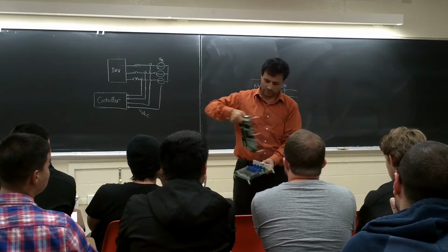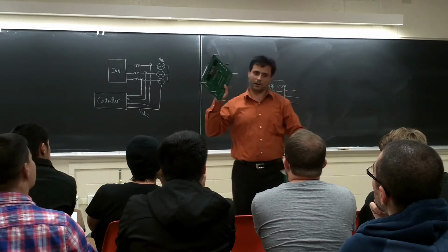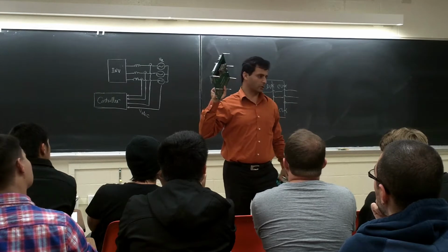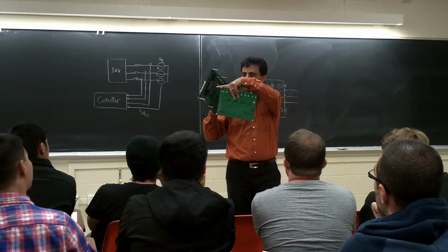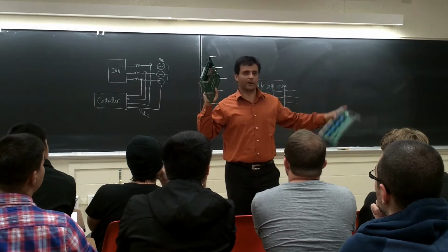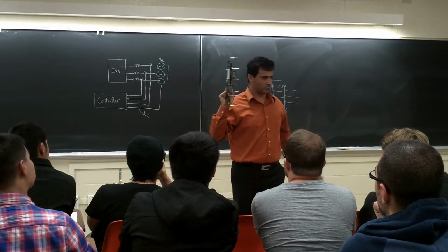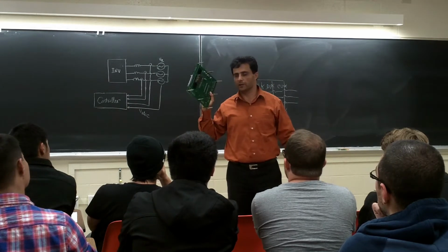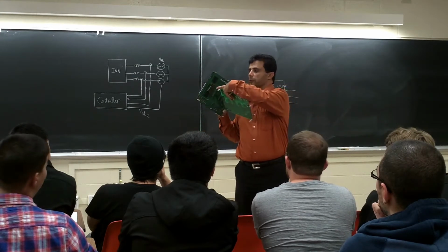I put some extra design here. Look at here. These are custom. I just want to make this board general, to be able to use it for everything. I don't want to use it for a fixed project. So basically, you can unplug this one. This is another signal conditioning board. For example, you have a new project, and the current and voltage values are different. For example, one project was 208, one project is 480. Maybe you are going to work with 1 kV. So basically, you can only change this board. You know what I'm saying?